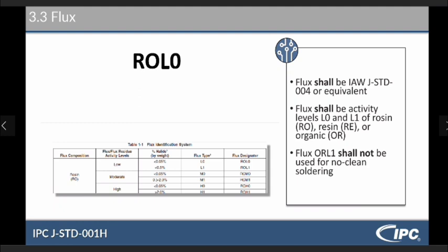Sorry about that, my headphones shut off for a second. So I'm looking for iron, and I want to know the assembly maximum contaminant weight percentage limit for tin-lead alloys. So I go to the second column in the table, and I go down to iron, which is Fe, and I see there's 0.02%. You may have a question on the test about this, so just get familiar with the table and pay attention to the notes. Notes are always important. We'll go over these before the test tomorrow.